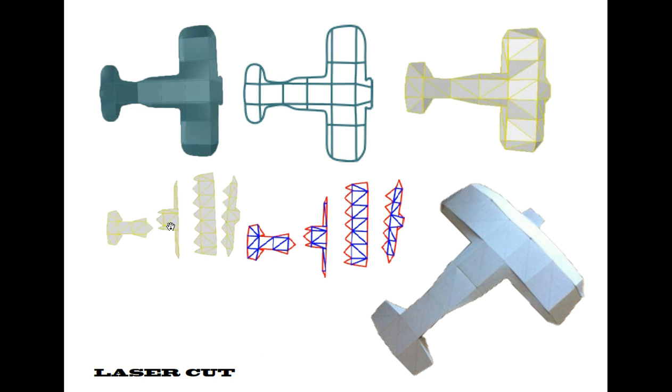For laser cutting, we used the bottom of my plane and extracted the wireframe and built onto it with triangulated surfaces, making the project bend and function the way I wanted. Then by unrolling it or flattening it, I could put it into the machine to get it cut.